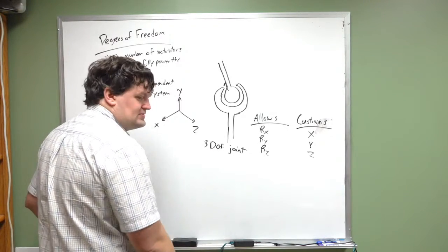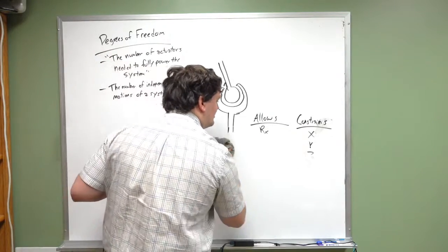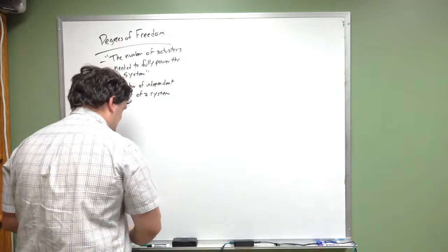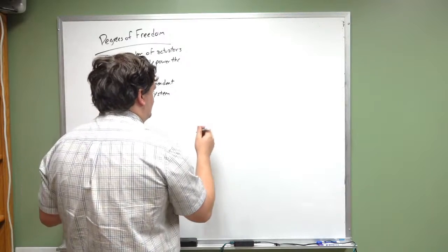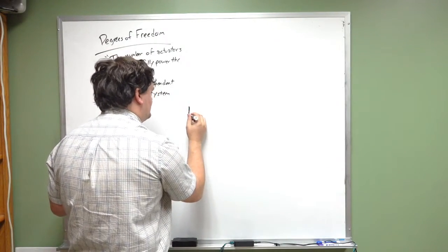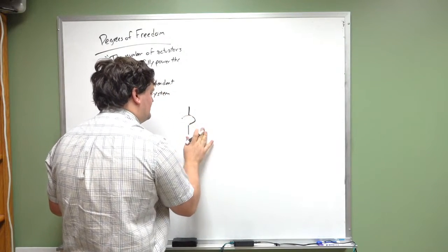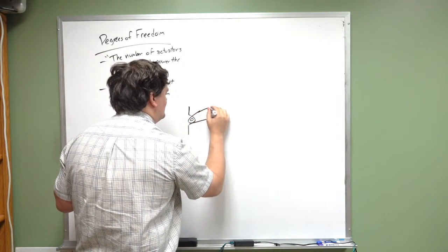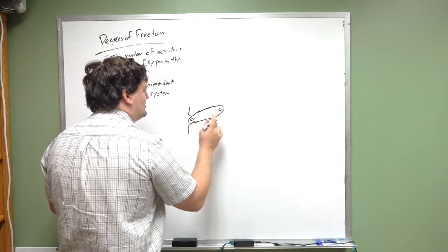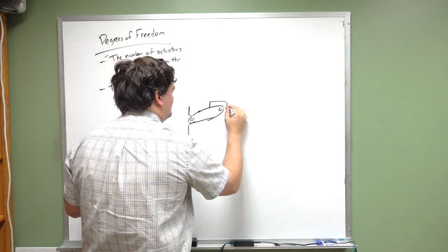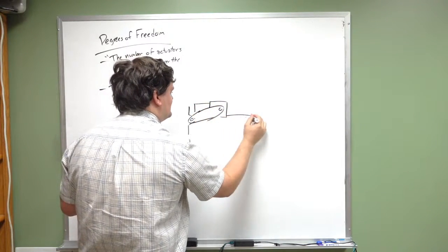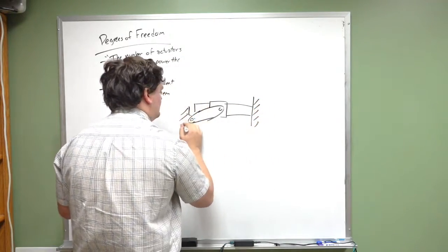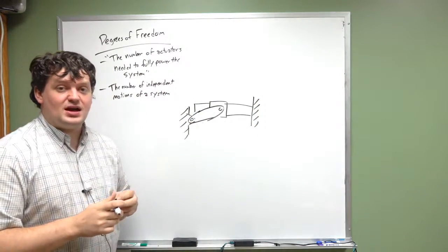So what happens when you have multiple joints getting together? Well, let's say I have a fixed component connected to the ground, a fixed component, 0 degree of freedom joint, whatever. We'll consider it part of the ground. I put in a revolute pin, and that revolute pin goes to a slider. And this slider slides on some kind of a rail where this rail is fixed to another wall. How many degrees of freedom does this system have?